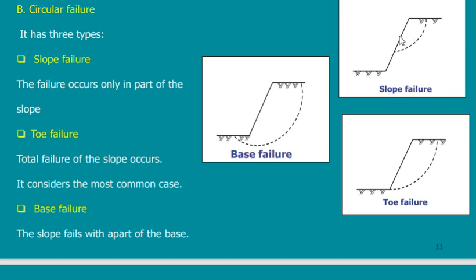Let's start from here. This small portion wants to fail, to fall. I will tell you to calculate the factor of safety. You will calculate the forces that are driving this wedge to slide. It is mainly the own weight of this wedge. And you will tell me that the force that is pushing this slope is because of this load.